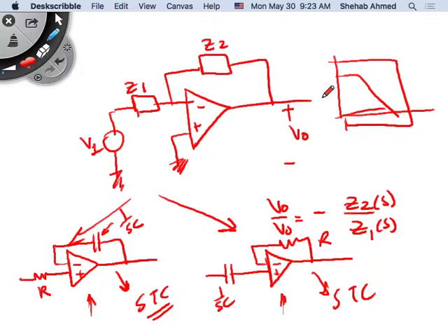If we have an input sine wave, and I want to see what the output is, I will take my transfer function that I derived, right? And then I have a gain at every frequency, and I have a phase at every frequency. I will plot phase at every frequency as well, right? And we did an example where we had the sine wave. But yesterday's example, we had a square wave, a pulse, right? This is not a sine wave.